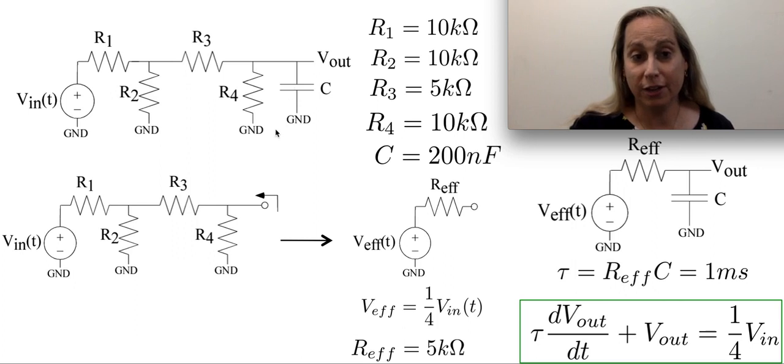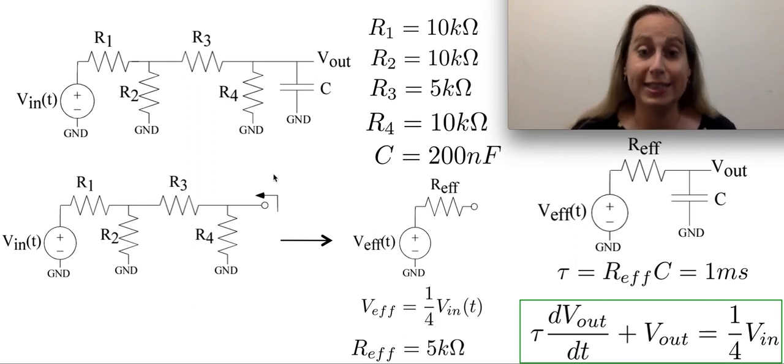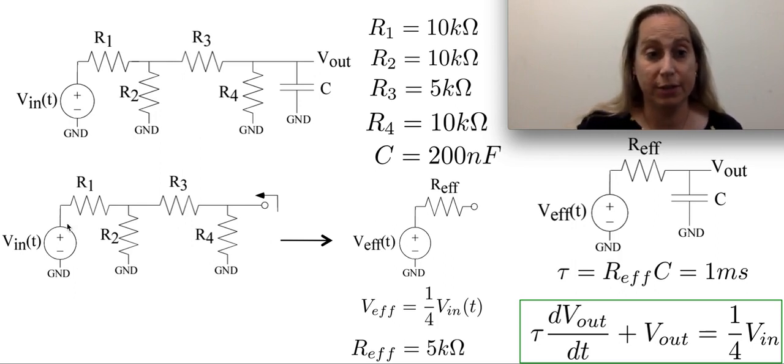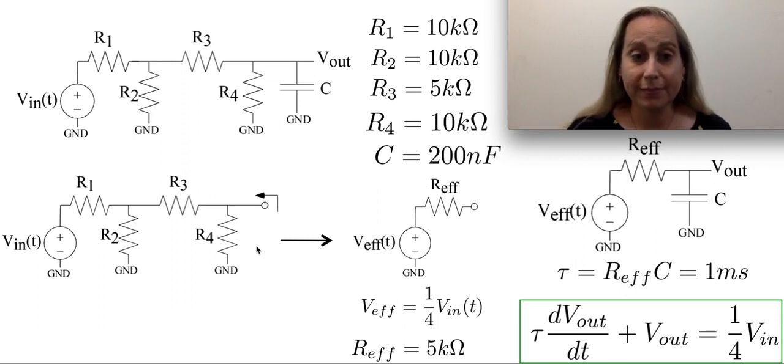And then the question is, beyond this capacitor, what is all of the stuff around here going to do? What you're basically left with is a very interesting question. With all these elements and particular values given, I need to solve what this whole structure is, and I need to ask what is the effective one-port equivalent of this entire circuit, and that could be either a Thevenin equivalent or a Norton equivalent. Because if I can do that, it gets me into an interesting spot.